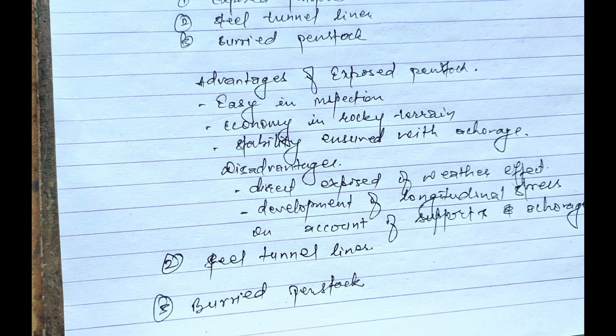The buried penstocks are usually fabricated from steel, concrete, or fiberglass. They can be either partially or fully buried inside the soil. The advantages and disadvantages of the buried penstocks are: as advantages, conservation of natural landscape, protection from landslides, storms, or man-made violence, and protection of pipes against temperature fluctuation with the help of a small overburden soil cover is possible.